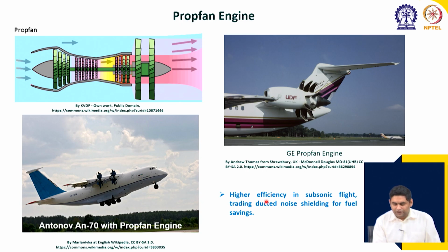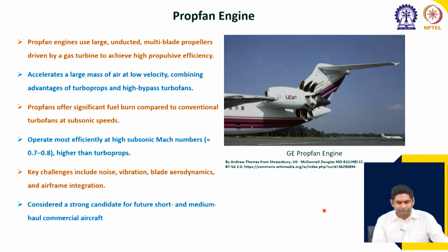So, this comes with higher efficiency in subsonic flight, but trades ducted noise shielding. So, it has more noise because no ducts are present, okay, but improves the fuel economy. So, it saves a lot of fuel. Okay. This was the idea behind prop fan.